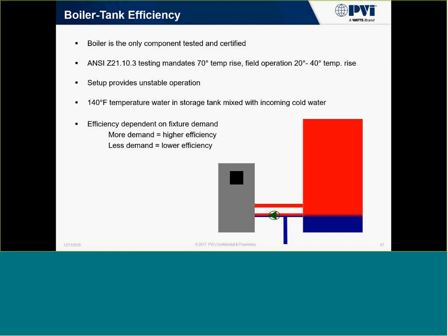Basically, the less demand, the more that heat exchanger needs to get flow from somewhere. For instance, if a building only needs 3 to 5 GPM of hot water, but the heat exchanger inside that boiler requires 20 GPM in order to protect it so it doesn't overheat, it's getting that other 15 GPM from that storage water tank, which is stored at 140 degrees.